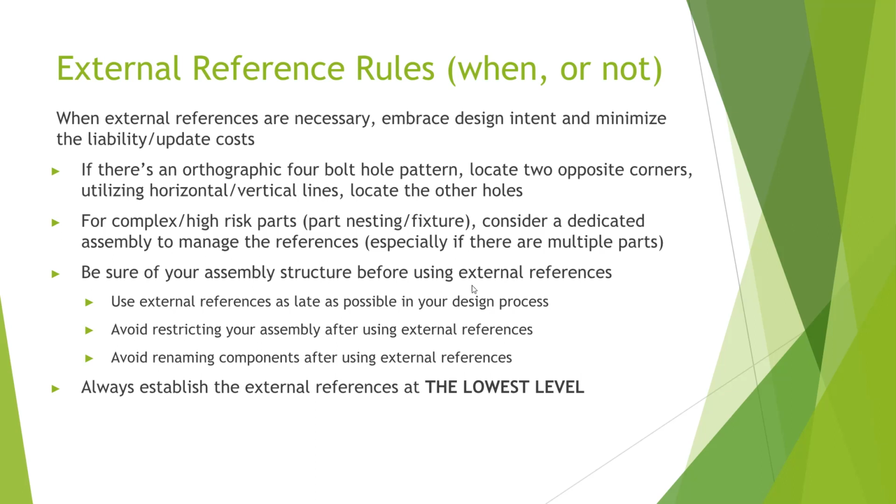And then be sure of your assembly structure. Use external references as late as possible. When you drop the Destaco clamp in your design, do you immediately put holes in it? No, we use distance mates and we say that's kind of where I want it, and then you adjust your mates. Then after the design review, after your sign off, after everything, then you go around and you plaster it full of holes. So do it last.